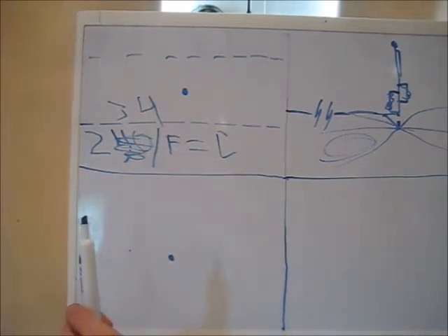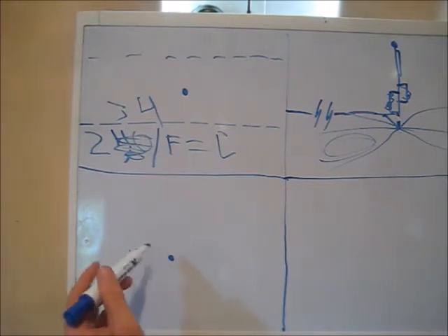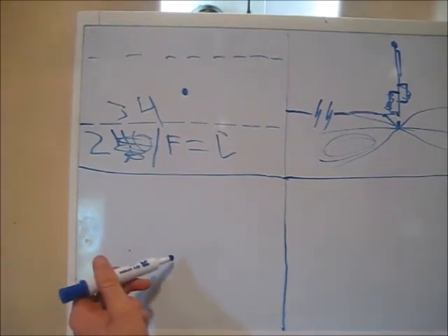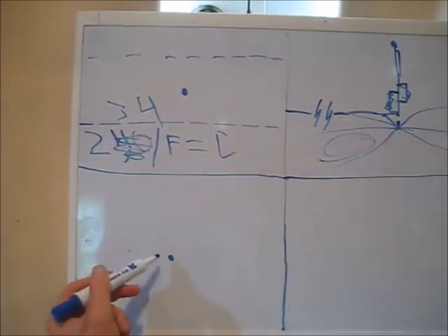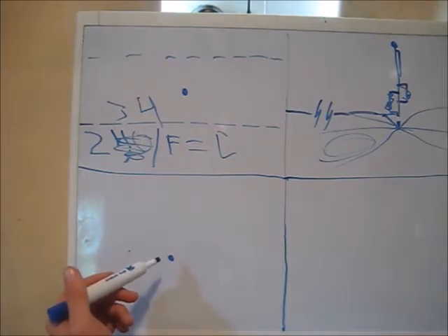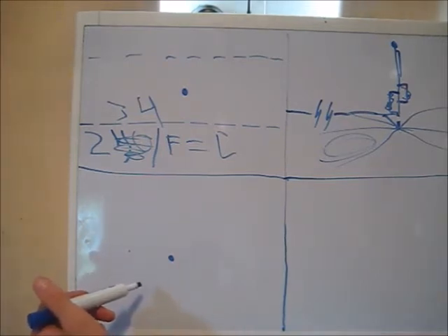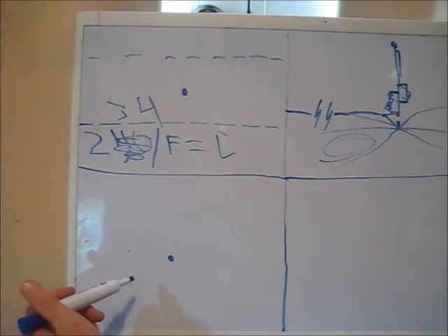Now, what do radials do? Assuming this is a top view, a two-dimensional top view of your antenna, your vertical is here. That outer shielding we talked about is running into the ground system. What does a ground system do? Well, right now, your antenna, your vertical out in the yard, is stuck into the ground. That ground is absorbing a lot of your signal, and as a result, it's not getting reflected properly.